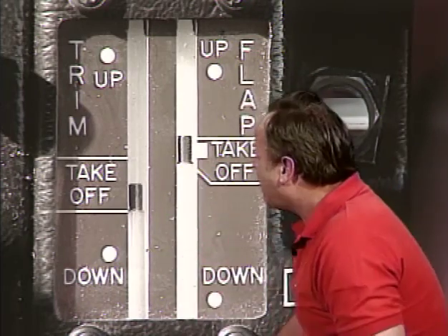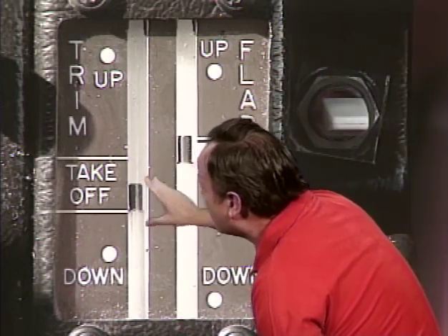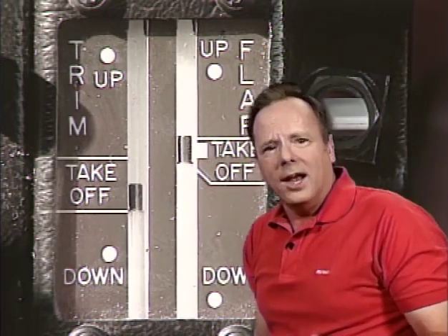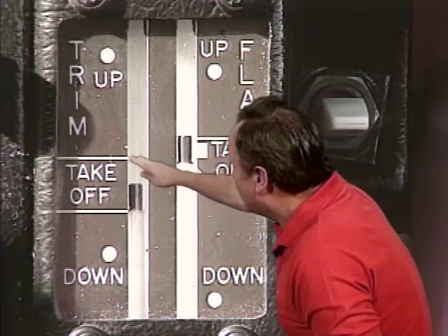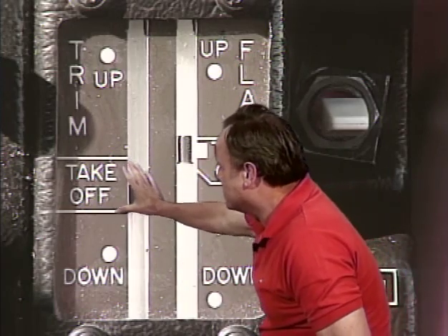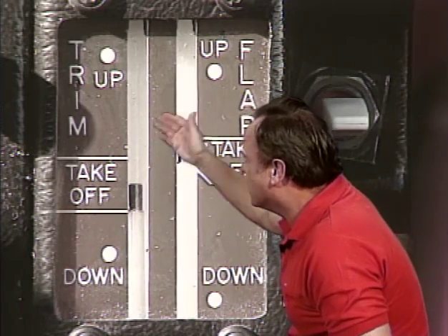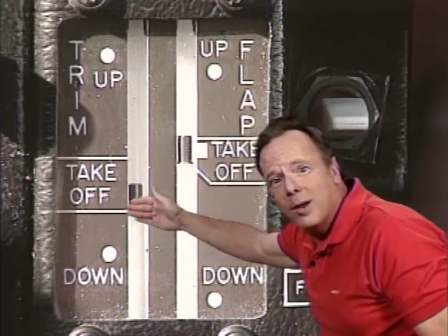How about a speed brake indicating system? No, it would not. How about an elevator trim indicating system? Does that have anything to do with the primary control surfaces of the aircraft? And the answer is yes. Elevator trim indicating tells you the proper trim position for, for instance, takeoff in this particular case, or maybe landing. And it has to do with the primary control surfaces because the elevator is one of those primary control surfaces of the airplane.